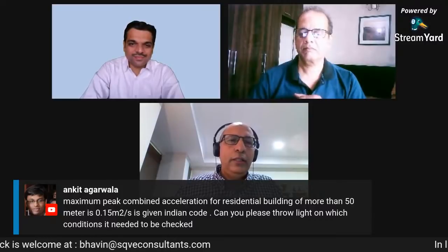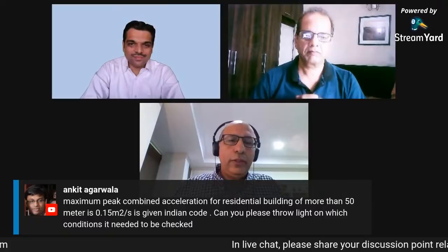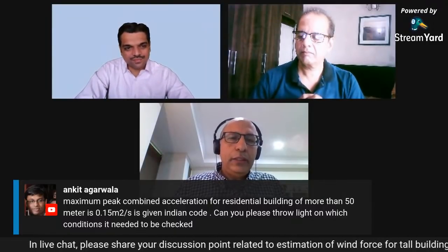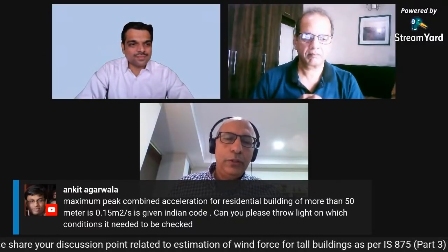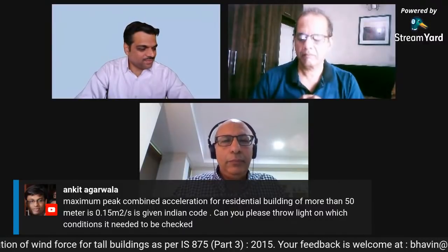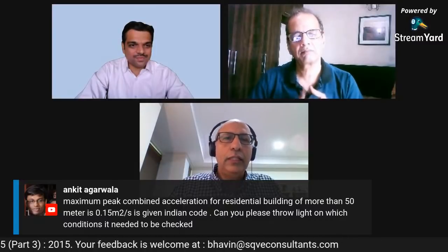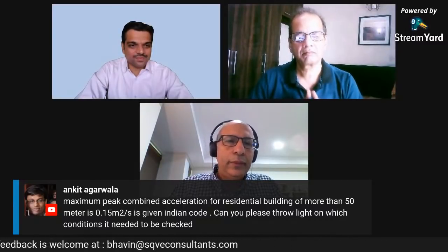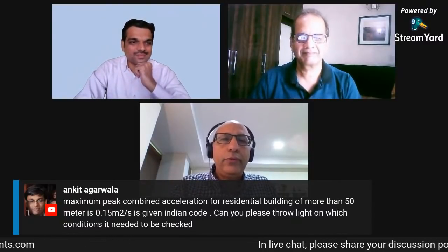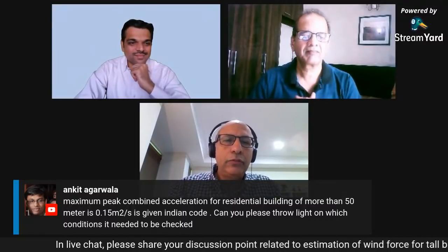So as the building sways at a higher frequency, as the frequency approaches 1 hertz, we tend to feel the effect of it, even subliminally, in terms of feeling tired, sleepy, whatever. That feeling comes over a large percentage of a population.